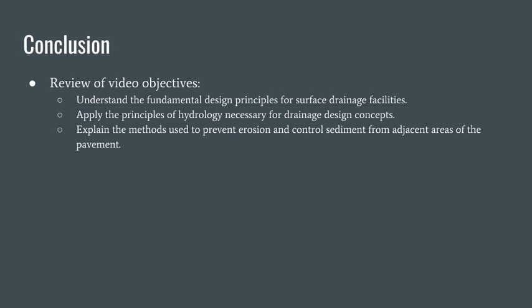In conclusion, drainage occurs due to highway runoff from transverse slopes, longitudinal slopes, and longitudinal channels, also known as ditches. There are major structures and minor structures that help manage this excess water. If a structure has a span larger than 6 meters, it is considered a major structure. If it is smaller than that, then it is a minor structure. This runoff can create issues with washout and sediment movement, especially in construction zones. Some measures to help prevent erosion are wattles, silt fence, riprap, intercepting drains, slope linings, and channel linings, as well as sedimentation basins, check dams, diversion dikes, brush barriers, slope drains, dewatering basins, and many more.